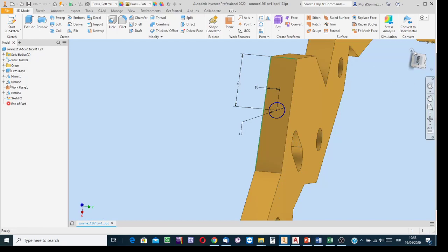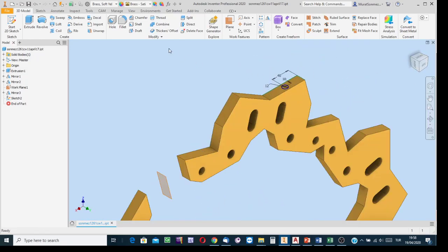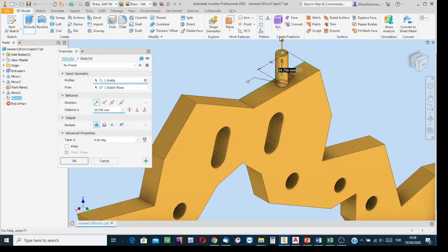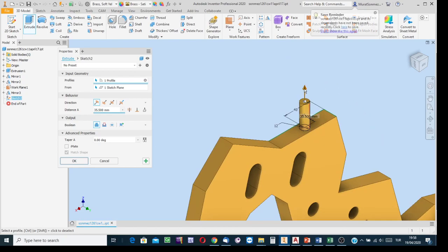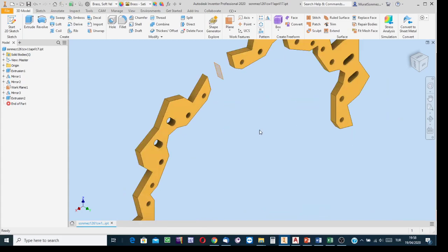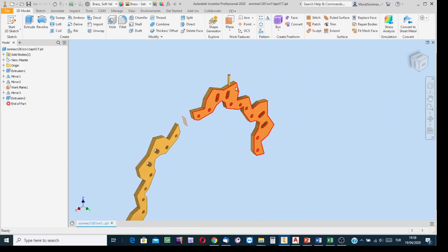Finish the sketching stage and then apply the extrusion process, okay, for adding such a cylindrical feature. Say that its length is 60. Yes. And then we'll create the mirror copy of the cylinder. Okay, relative to where? Relative to a certain surface. Okay, here is the plane, mirror copy.